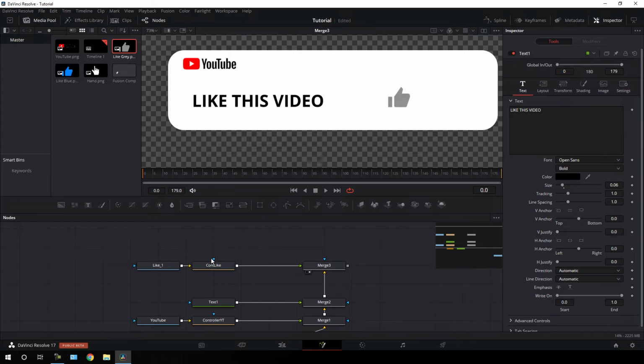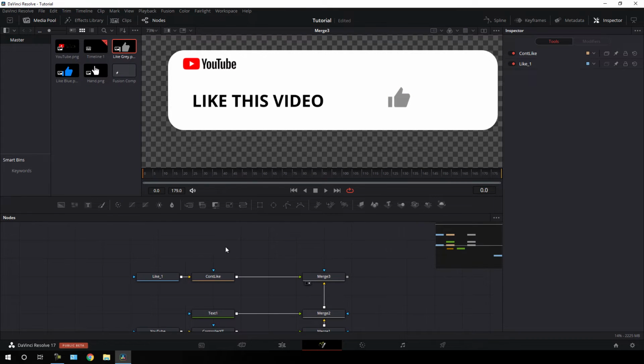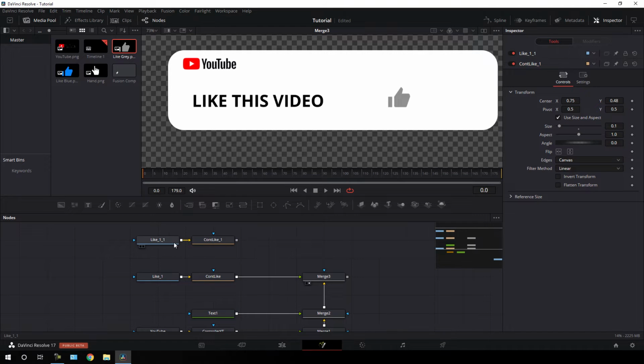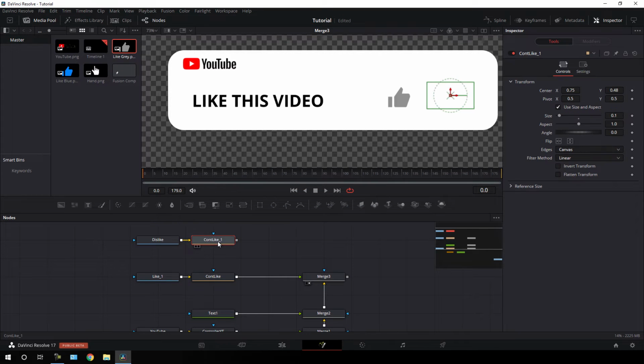So what we have to do, just select these two nodes, hit Ctrl C to copy, double click on this blank area, hit Ctrl V to paste. Drag it over here, select this, hit F2 on the keyboard, call it dislike. Select this, hit F2 on the keyboard, and this is going to be controller dislike. All right, and do the same thing, connect this controller dislike with the main output.